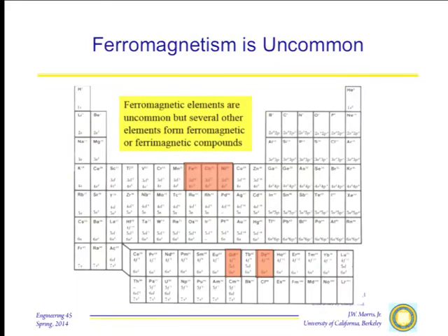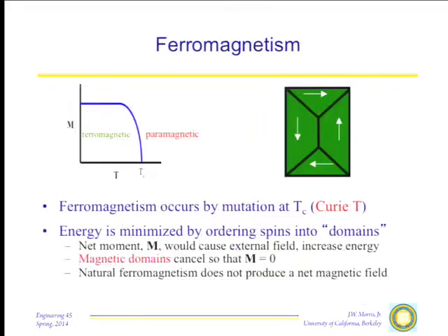Cobalt, the hexagonal, let me get this wrong, hexagonal phase, it's hexagonal or cubic. I think the hexagonal phase is the ferromagnetic one, only one is. Nickel. Among the rare earths, only gadolinium and dysprosium are ferromagnets, and very powerful ferromagnets because they're out here in the middle of the sequence and have very big magnetic moments. Unfortunately, these are also quite expensive materials.